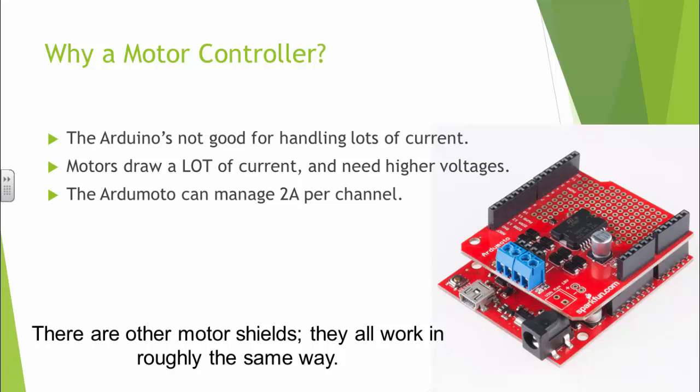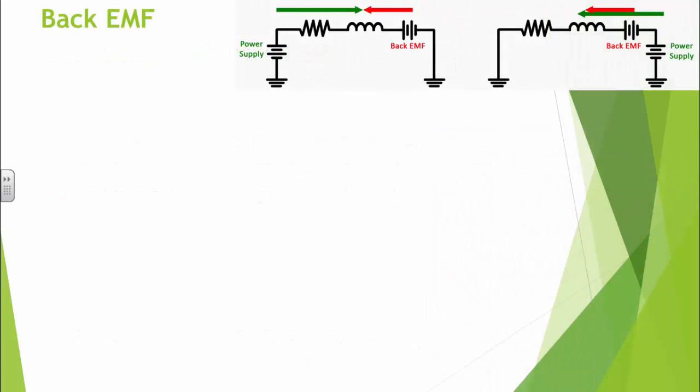In case you're curious, SparkFun are not the only ones who make motor shields. There are lots of other motor shields, but they all work in roughly the same way, so we can use it as our example. So now we've got our current taken care of, and our voltage taken care of with our motor shield. We might as well have a quick discussion about this thing, back EMF.